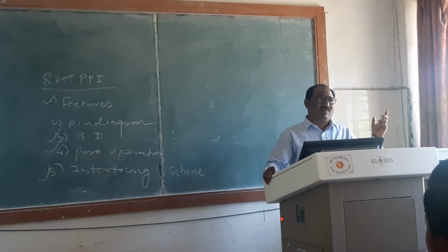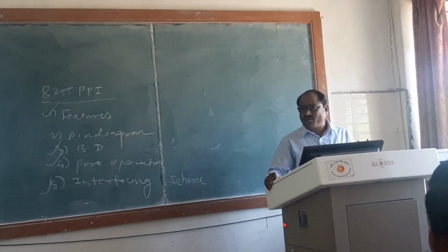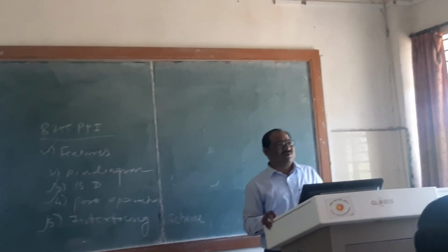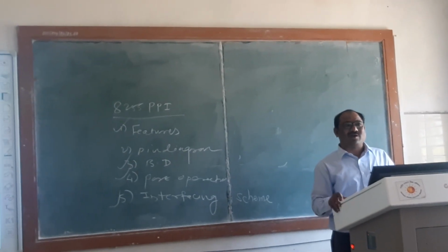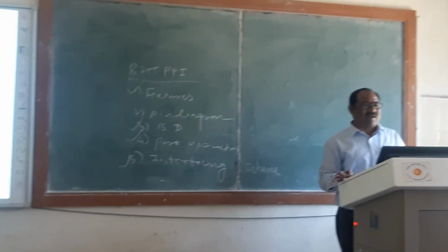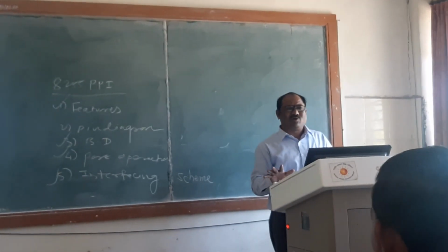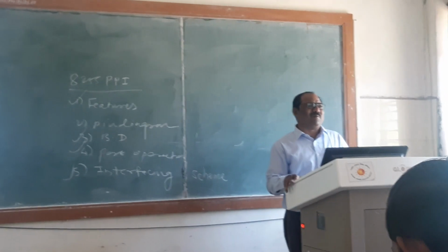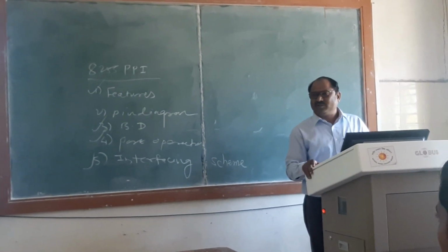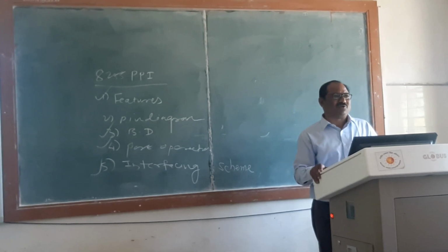This is the 5 megahertz clock provided to the 8085 microprocessor through the quartz crystal. The quartz crystal is an analog clock, an analog timer we can say, and this is the digital timer. Now, there are two ways to provide this. With the 8253 and 8254, you can provide a train of pulses, that is, a clock to the 8085 microprocessor.